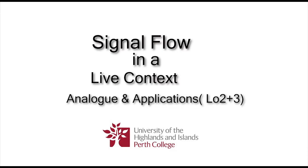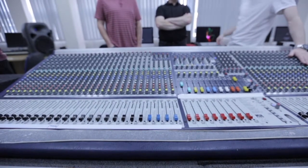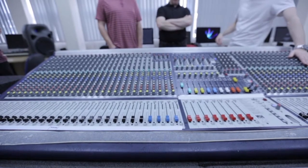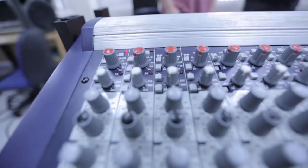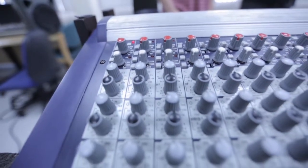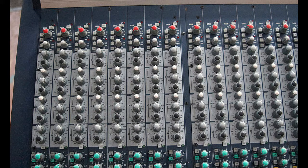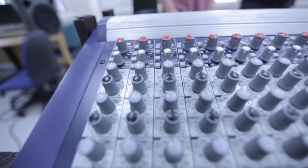This is a demonstration of the signal flow through an analog desk used in a live application. I'm going to use the MH3 owned by Path College. The signal starts by entering the desk through the connected inputs. This signal goes through the mic preamp, passing through the channel strip. Then it passes through the equalization section. The MH3 has a semi-parametric equalizer.